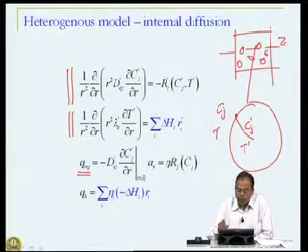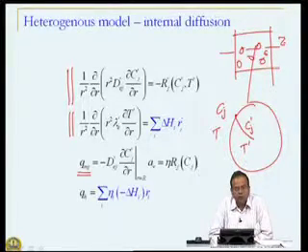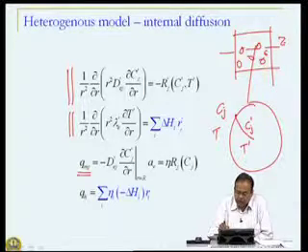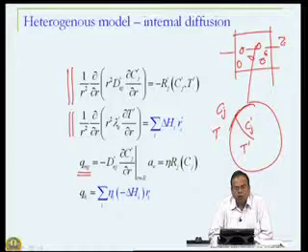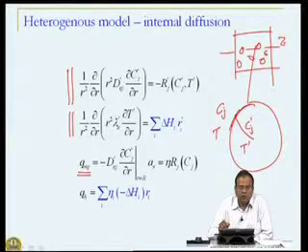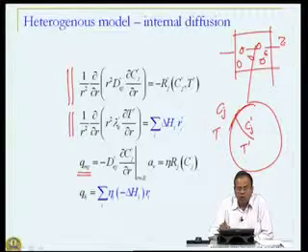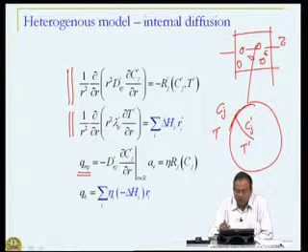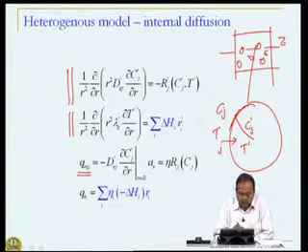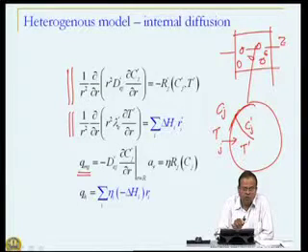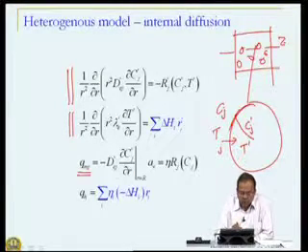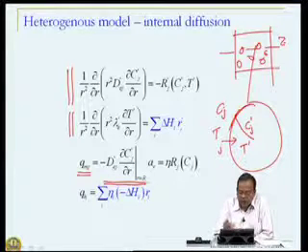So, now if we position ourselves into this bed, all that the bed will experience is that there is a diffusive flux of species J at the surface, because there is no reaction in the bulk liquid, the reaction is only inside. So, all that we will experience if we are in the bulk is that J is diffusing in the catalyst pellet. So, the mass transfer or rate of generation of J, QMJ, must be this diffusive flux at radius R of the catalyst pellet.